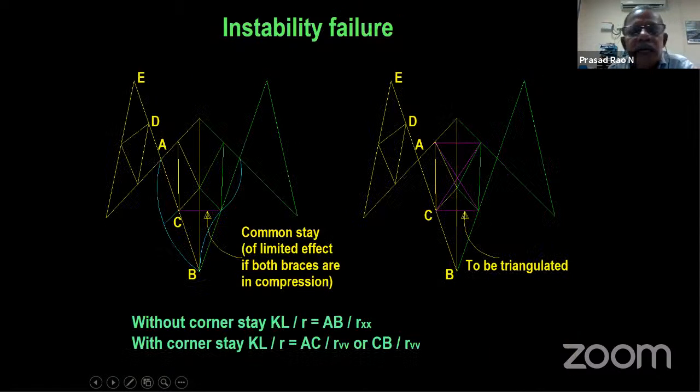So how to use the secondary bracing? See, this is a system where we have an isolated hip bracing used, and there is no triangulation in that, from the other side, if you see from that corner, there is no triangulation. So this should not be used like this. You should use the yellow and magenta color arrangement. You have to fully triangulate the hip bracings also, not only in this elevation, on the hip side also you have to fully triangulate.